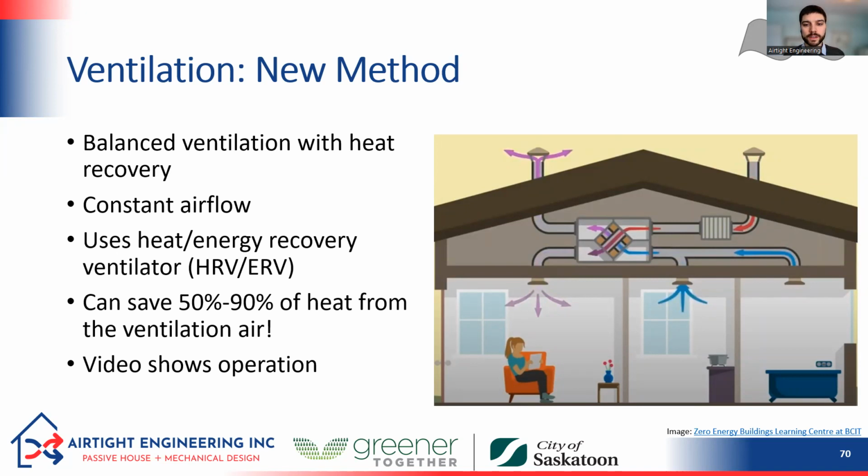So we can see the benefits of this new method of ventilation. We get better control over the fresh air. We get to distribute the fresh air into our houses more evenly. We get more continuous ventilation. We have the opportunity to filter that air. We get to recover a lot of energy from the ventilation air. Overall, it's just a great strategy and a pretty simple machine, really. It's basically just a heat exchanger core, which has no moving parts, and then two fans and some dampers. So it's a great option.